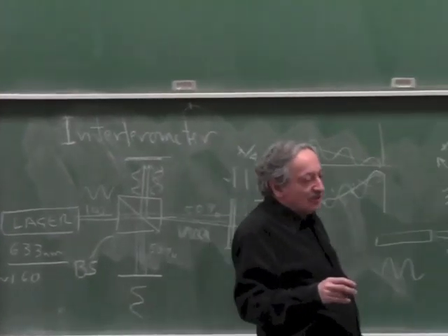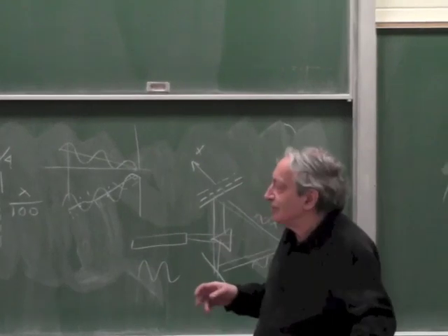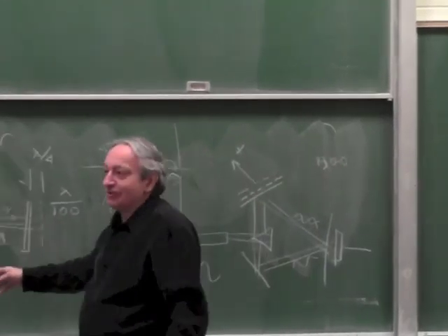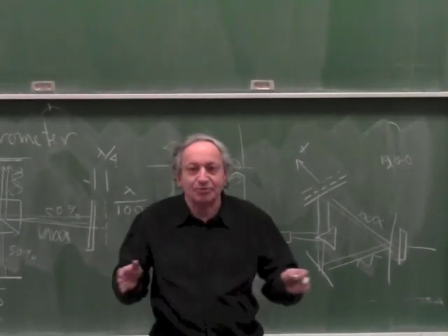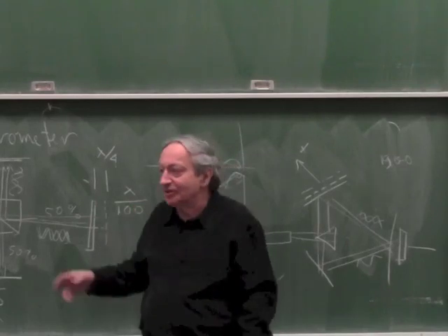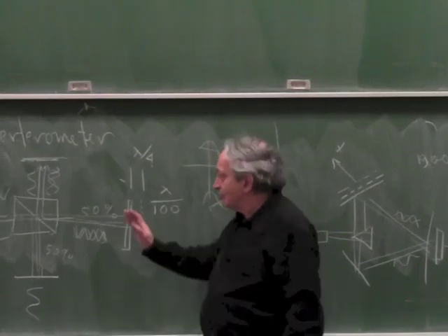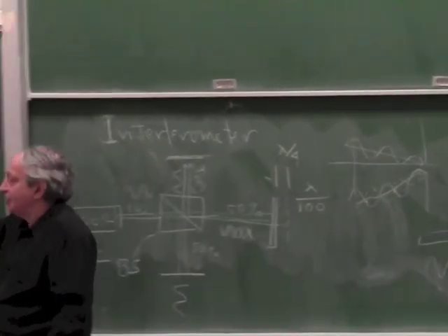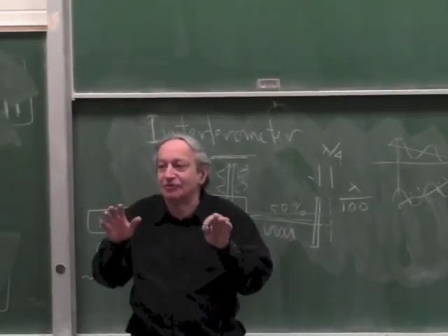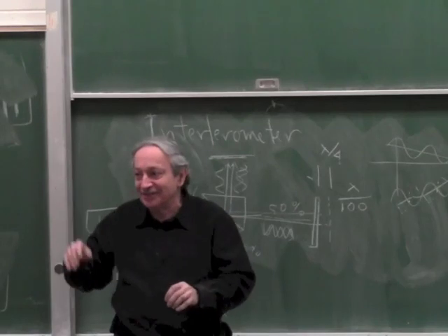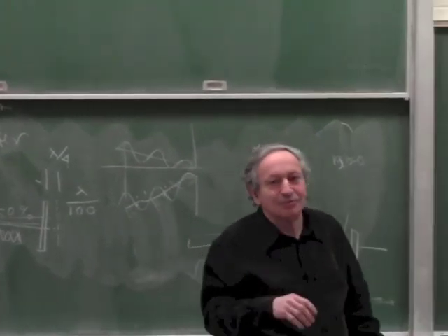Okay, so out of this whole idea of ether and all kinds of other ideas which turned out to be a mistake, something very good came out, which is an interferometer, which is the base sensor for very precise measurements, both linear and also rotation. You can build it so that it measures rotation, also measures tilt. Right? If this would tilt, then this whole band pattern will shift. And you can have two, so you can see if they shift together, it's motion. If one shifts and the other shifts the other way, it's tilt.